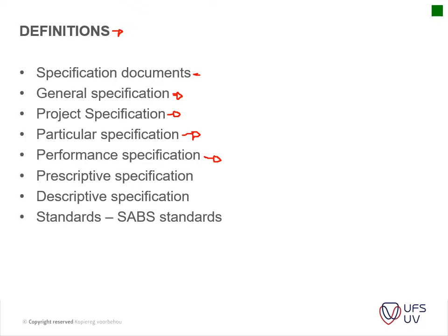That type of specification. Then prescription specifications, where you would prescribe that the contractor work maybe at night, because during the day it's occupied by tenants and they do not want to be disturbed. So you would have specific prescriptions: only this access gate may be used during the construction process, etc. And then descriptive specifications will just be supplementary items describing how a specific item is fitted together.